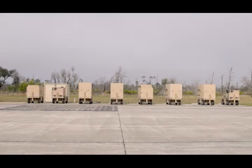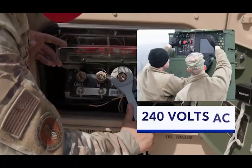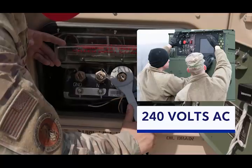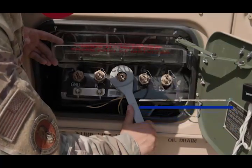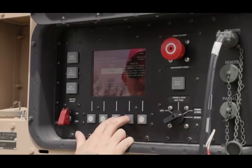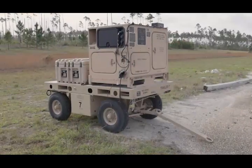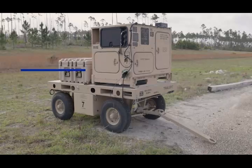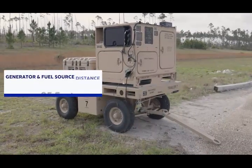Each EALS kit includes 2 generators, stored in trailers 6 and 7. The system operates at 240 volts AC, which is much safer than the high-voltage legacy systems. However, the lower voltage and smaller wire size constrain generator placement due to potential voltage drop. If an auxiliary fuel supply is used, the generator should be placed within 25 feet of the fuel source.